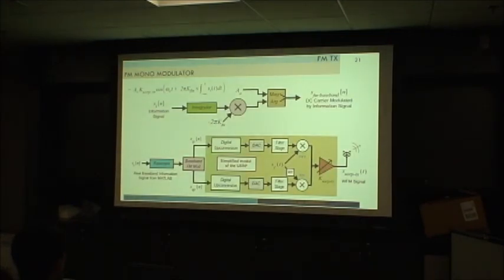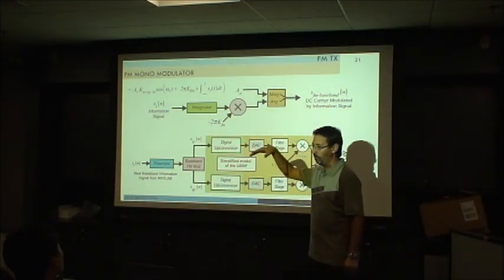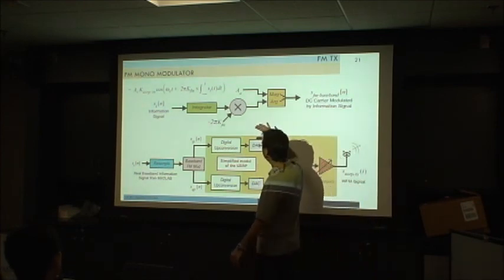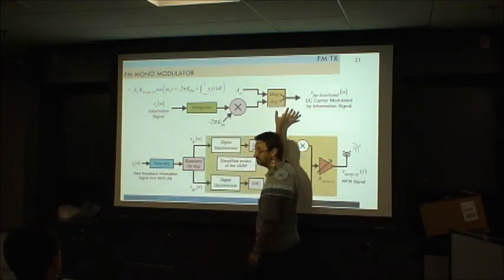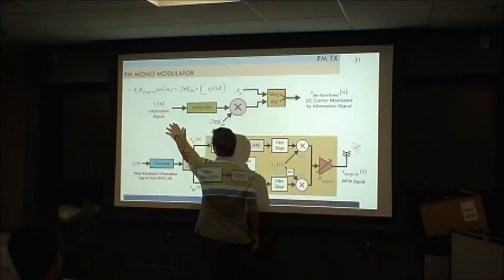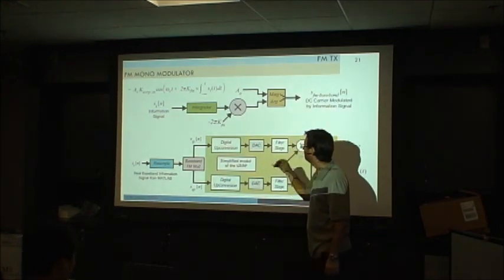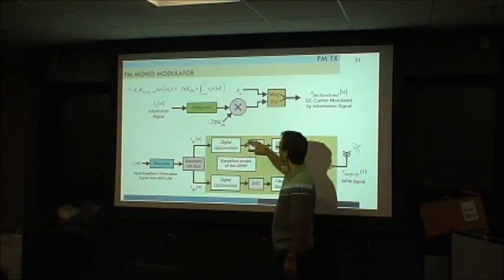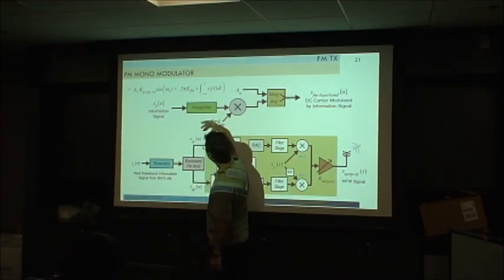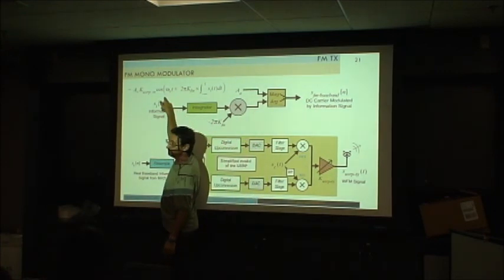If you remember the first slide where I was talking about how a VCO could be an FM modulator, that VCO has this architecture. That is the one that we want to use. So we have the signal here, and this is the sensitivity of the VCO. We are doing this, plus some constant factor that will give us the base frequency.